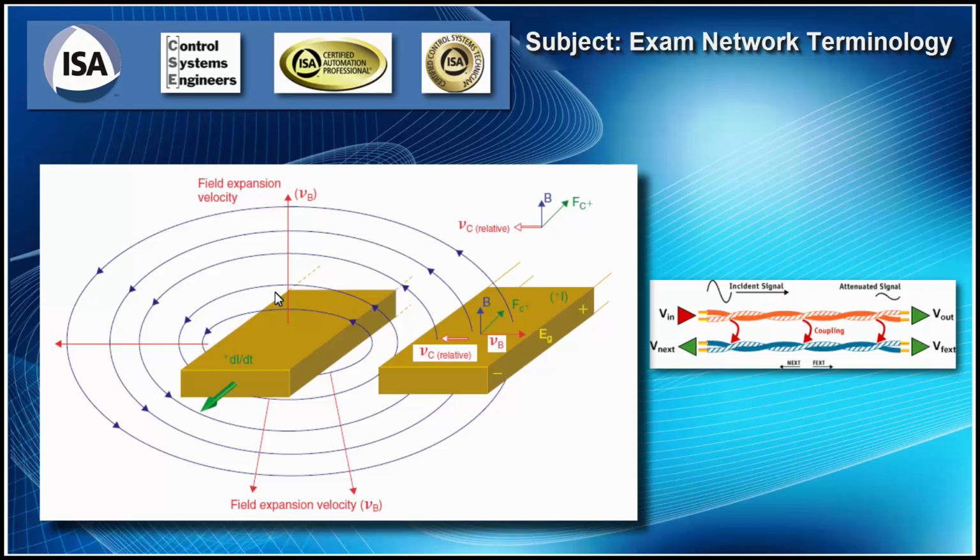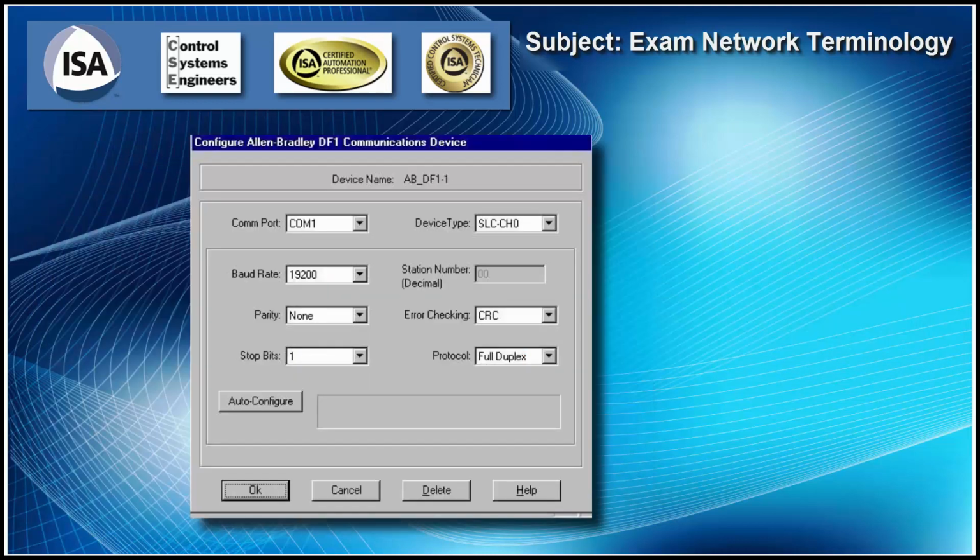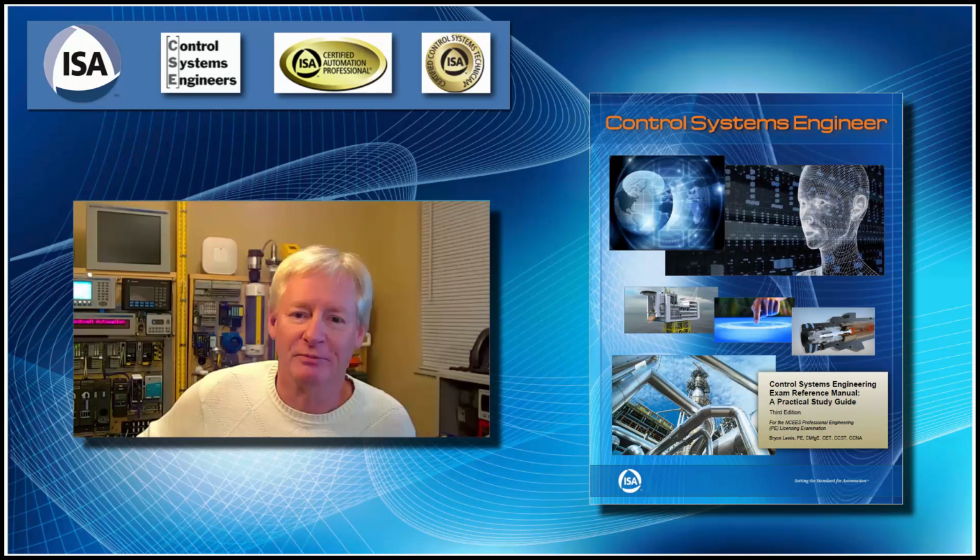Also, they're talking about parity. Parity is how many bits you're using, and typically this is on a serial connection where you're trying to hook a serial connection up to a PLC to program it. It's used with error checking, and you set it for either even, odd, or none. Depending on the setting, it'll run an algorithm to check the bits and make sure the checksum is either even or odd, or you can say none. So they'll talk about the parity and the error checking, which will be like cyclic redundancy check, or BCC. We've pretty much covered the specifications now.